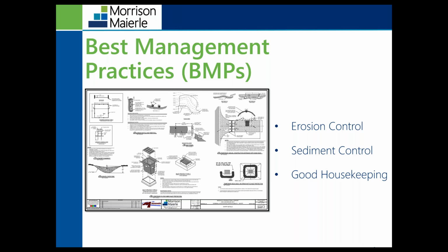So when we are describing best management practices, there are 3 different BMPs that we're going to be looking at installing. We have erosion control BMPs, soil stabilization to protect the soil surface against erosion mechanisms such as water or wind. Really, when we're looking at erosion control BMPs, we're trying to keep the dirt in place. Underlying layers of soil are more susceptible to erosion, so we can keep that vegetation there, keep the topsoil there, prevent erosion from occurring, keep that dirt in place, keep that pollutant at the source right there, which really minimizes the amount of pollutants that can be discharged in that stormwater.